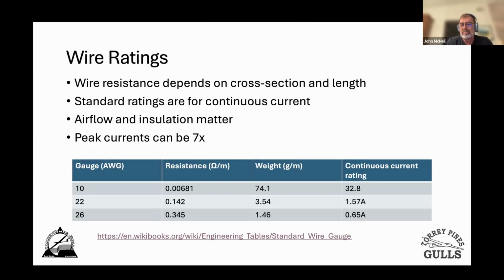So you can fill in why there are battery fires from there, because of hydrogen and oxygen. Yeah, so we're going to get back to safety, and I'm not going to talk about it now, but as long as you just raised it, these packs spontaneously combust. We've all heard stories. It's real stuff. Also, if you damage them, if you puncture them or they're creased, look at your packs. I fly puffed packs, and my metric is this: when I go to put them on the charger, each cell needs to be within like 0.02 to 0.05.